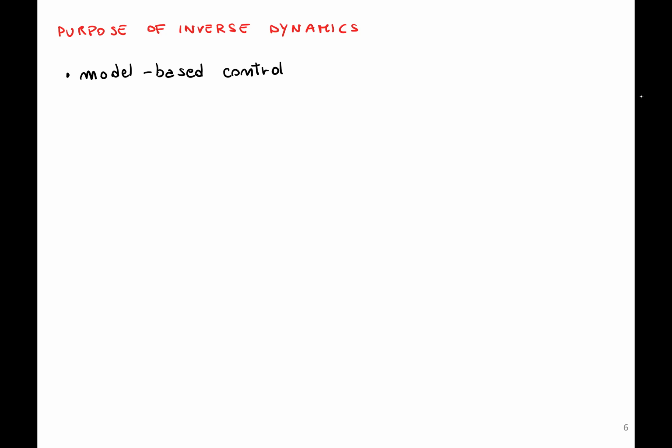So it's releasing the feedback part of the controller from the effort to reduce the tracking error, and this allows you to have higher performance. Or again, as with actuator sizing, as we said before, you can check the torque to achieve a certain motion and size the actuators. Okay.